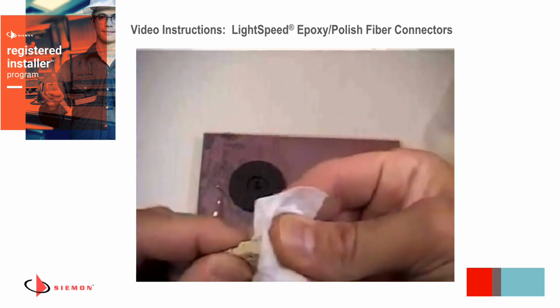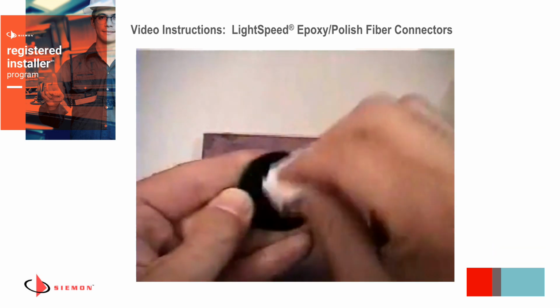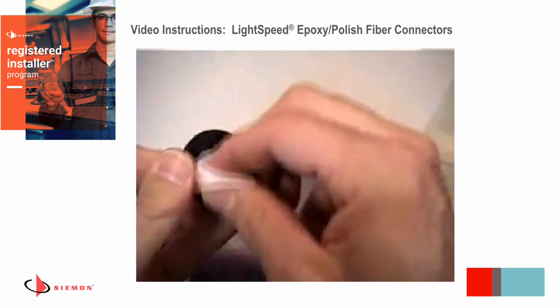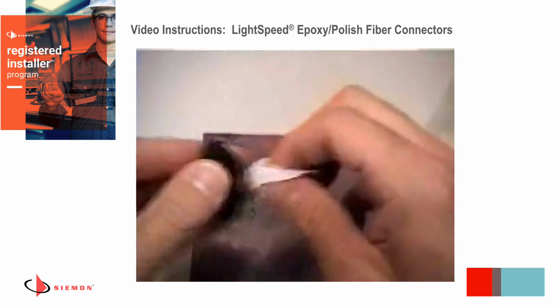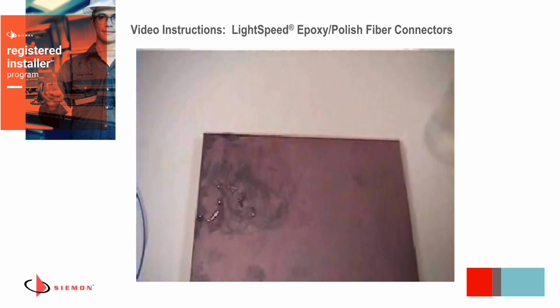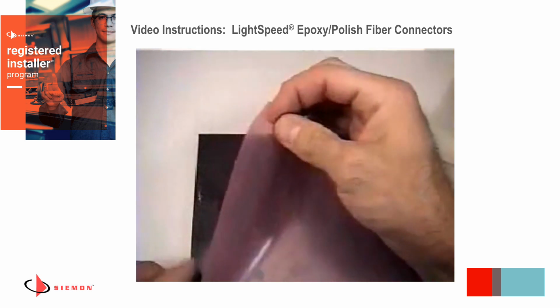Next, remove the connector from the polishing puck and clean the ferrule and puck to prevent particles from transferring onto the next film. It is also important to thoroughly clean the surface of film prior to storing to assure ideal conditions for the next connector. Allowing the film to dry without cleaning off the debris can adversely affect subsequent connectors.